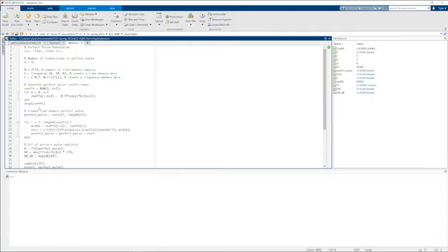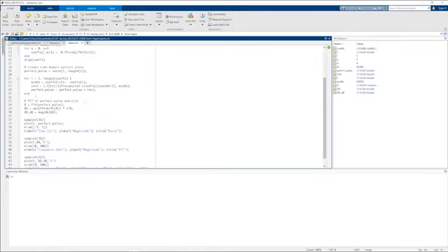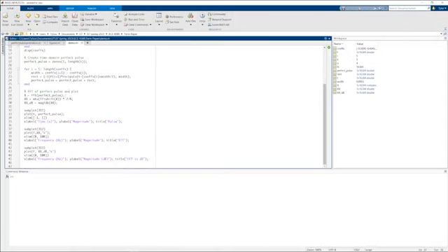Here's a quick rundown on how to generate a perfect pulse in MATLAB. The first step is to generate the coefficients of your perfect pulse. In this case, I'm doing calculations for a P4 pulse. The next step is to generate the time domain perfect pulse. This is done by summing together a bunch of rectangle functions that start and stop on the values of the coefficients for the perfect pulse with alternating amplitudes of 1 and -1. Then we take the Fourier transform and plot.